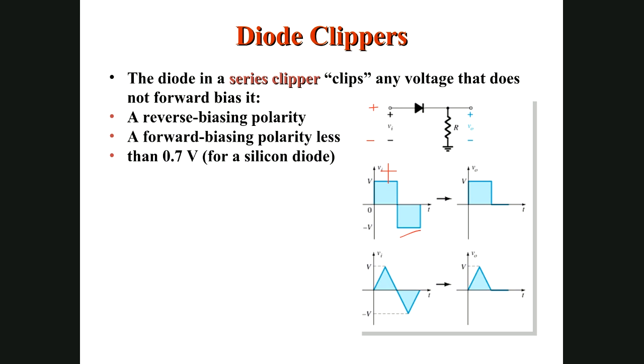Your diode will be forward biased, because the P side is getting positive voltage and the N side is getting negative voltage. In forward bias, the diode behaves ideally as a short circuit, an easy way for the signal. Thus, in the output, almost the whole signal will be there. Whatever is in the input, the same you will get in the output.